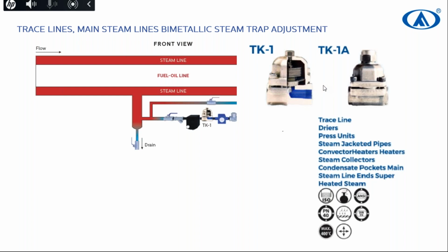If you use 20 degrees Celsius temperature difference, you can use more energy in your line, and also there will be more condensate collection before your steam trap, which means the condensate discharge amount will rise. So according to the system, you need to adjust in some cases, not all cases. I hope it answers your question.